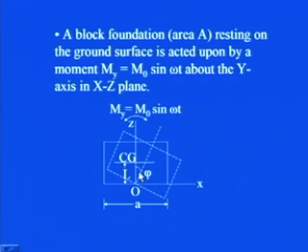So, how can we analyze this particular situation? You have to get the corresponding value of the soil spring constant, and for that you first have to get the natural frequency when this type of vibration is occurring.